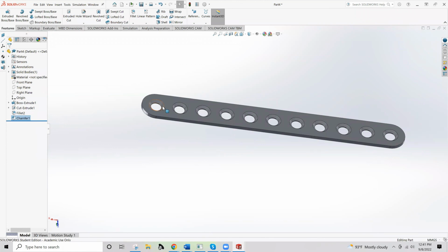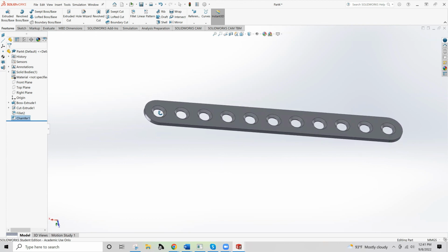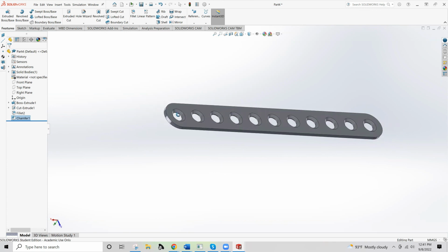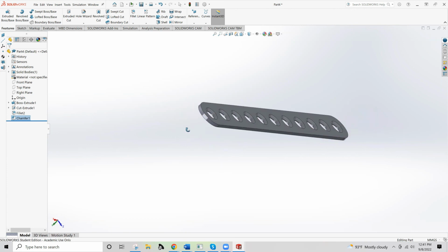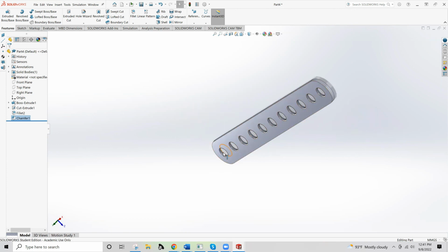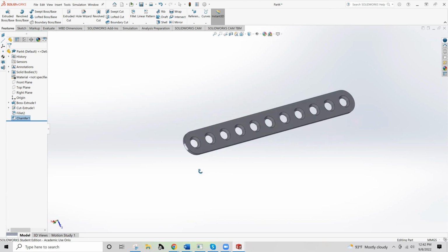Exactly. Something like being able to have the head of the fastener sit flush. So that's one of the instances where you might want this kind of a feature, but you want it only on a certain side. And maybe on the other side, you want to deburr, which would be more like a fillet, to deburr the hole so that you could get hardware through this.